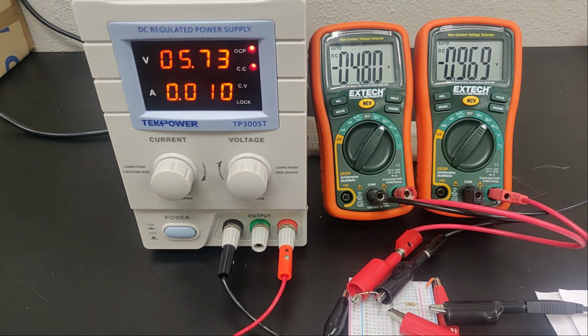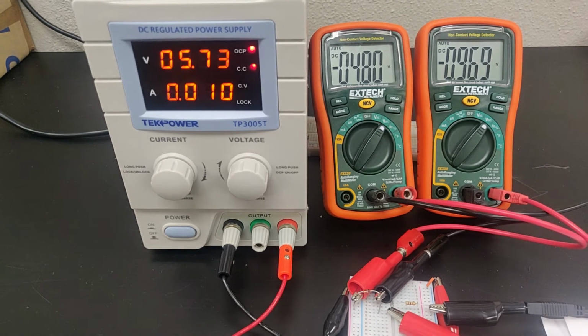Okay. With those data points, you should be able to calculate the current from our two resistors, and you should be able to plot the characteristic voltage versus current plot for our Zener diode. That concludes part A of the experiment. With your data, you should be able to plot the voltage versus current plot of the Zener diode. You should have 3 in all, between the 2 from the signal diode and the 1 from combining your data sets, the one that you get from here.